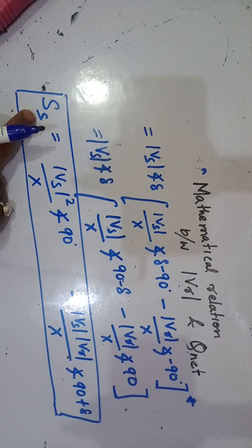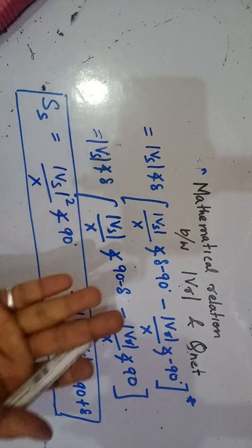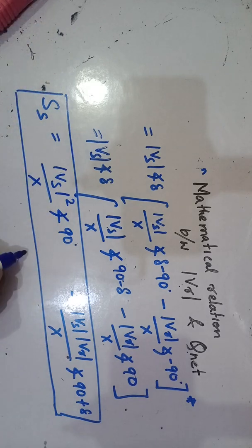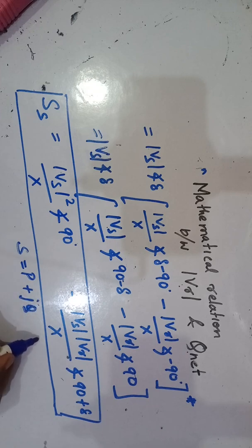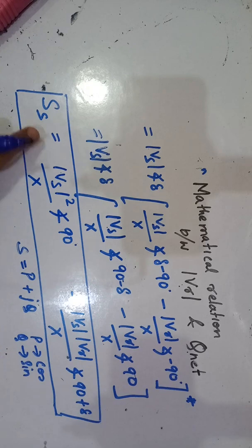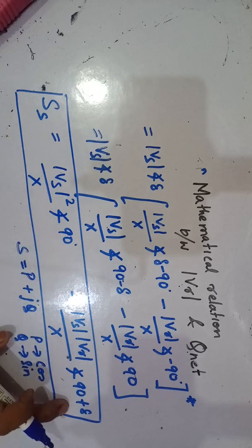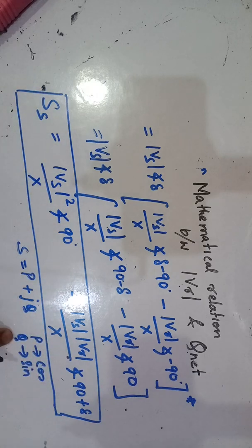So this is a complex power. You can convert this complex power, as we know that this complex power will have two parts, P plus jQ. P is the cosine component, Q is the sine component. So if we take the sine component of this, it will give you Q. If we take the cos component, it will give you the real part or cosine part.